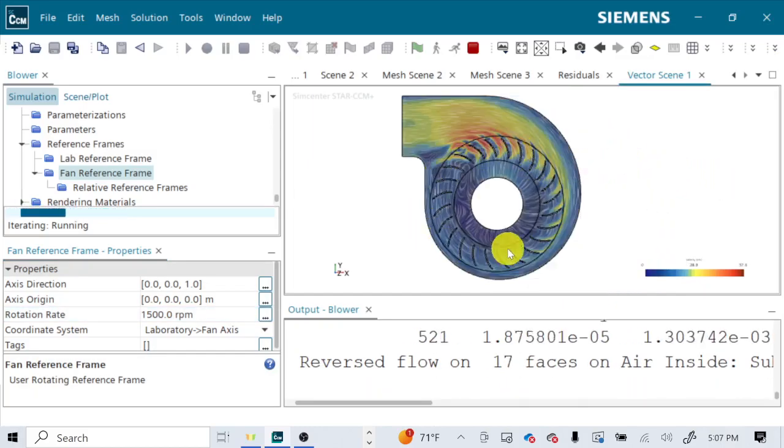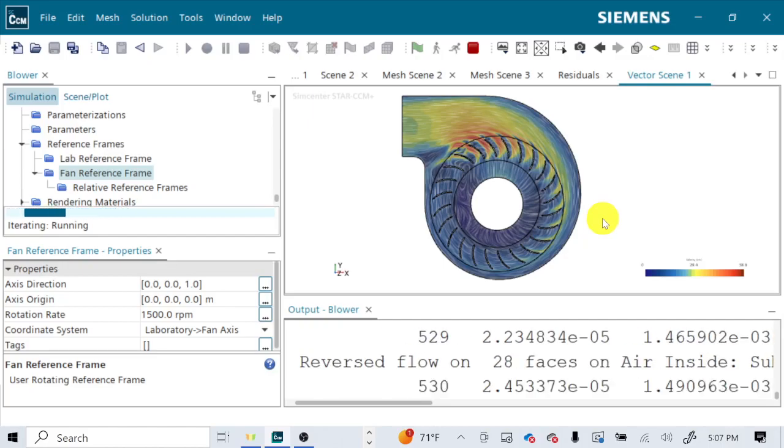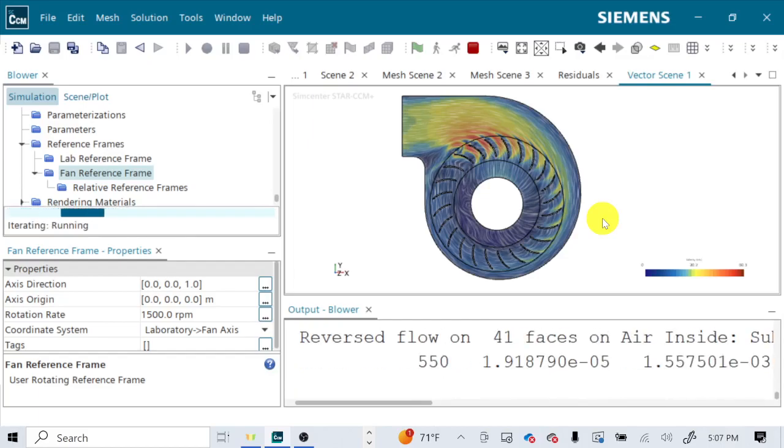So we made a completely separate region for that. And then more or less we set it up like we normally would. We had an inlet with some conditions, an outlet with some conditions, and we told it that that rotating region is rotating by specifying a different reference frame. Like I said, it is a moving reference frame simulation. It's not physically moving the blades at all, but it's acting like they're moving based on reference frame math. I refer you back to dynamics for all that good stuff, but as applied to fluid mechanics.